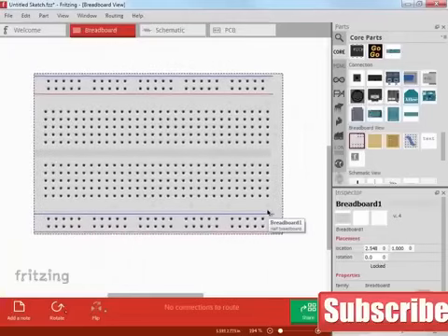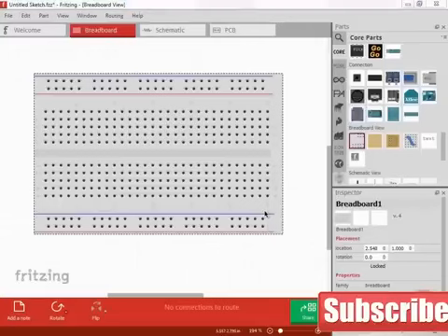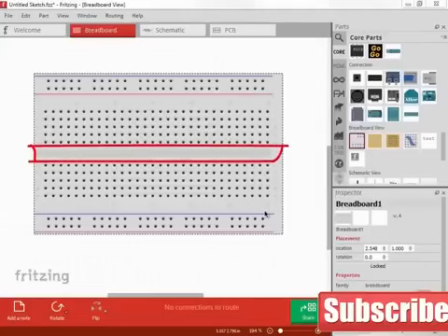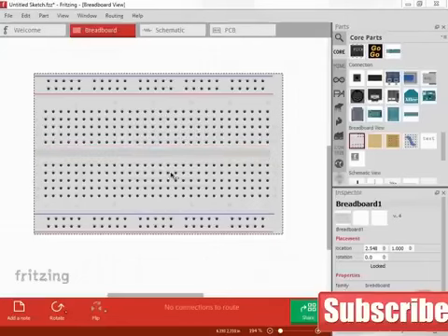It is important to understand how the contact points are connected. The breadboard is separated down the middle with a channel. This is typically where an integrated circuit would straddle, so that all its pins land on isolated columns of contacts. The highlighted pins show areas of common electrical connection.